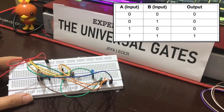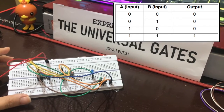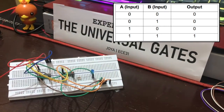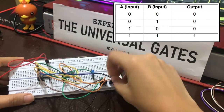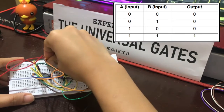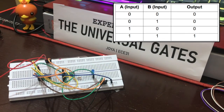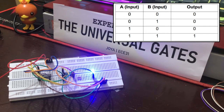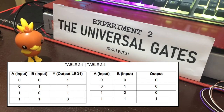The results of AND operation using NAND gates show that when both of the input terminals are 0, output is 0. When only B is 1, output is 0. When only A is 1, output is 0. And when both of the input terminals are 1, output is 1. The results of tables 2.1 and 2.4 show exactly opposite output results.